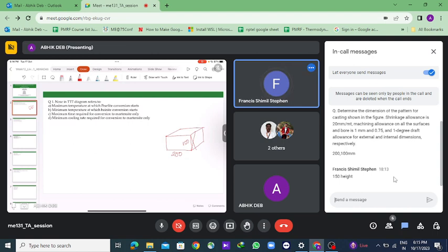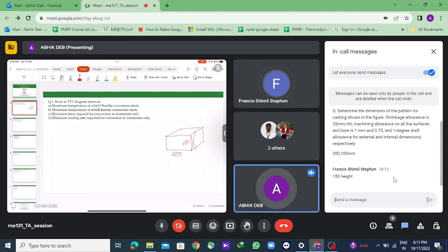No, we have to taper like this. That is a tapered structure. The cavity should look like this. The reason for this is so that when you move it out, there is an increasing clearance in this direction. If you give the taper in such a way that the cavity ultimately becomes like this, then